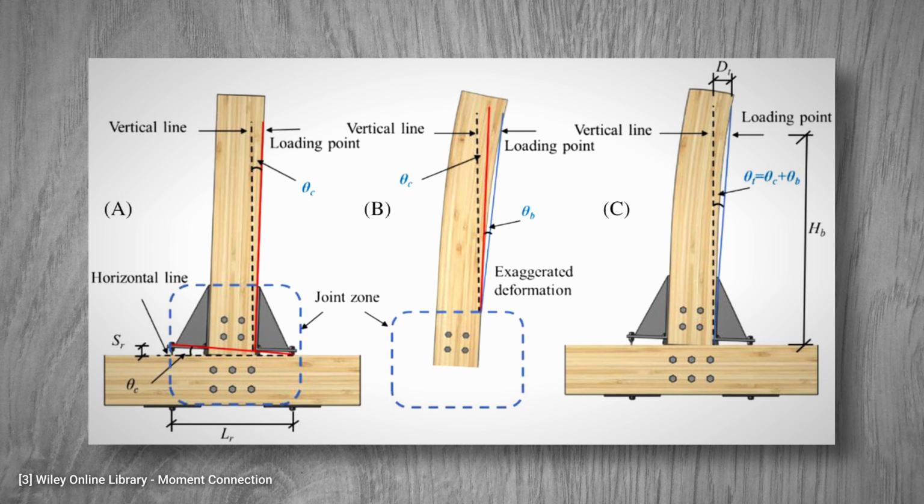Loads in the post and beam system are distributed through point loads at the column locations. While beams help spread the load from the floors and roof above, the system does not provide as uniform a load distribution as load-bearing wall construction. Shear resistance is relatively weak in post and beam structures. Additional bracing or moment-resistant connections are often required to handle lateral forces, unlike load-bearing wall systems, which inherently resist shear forces.